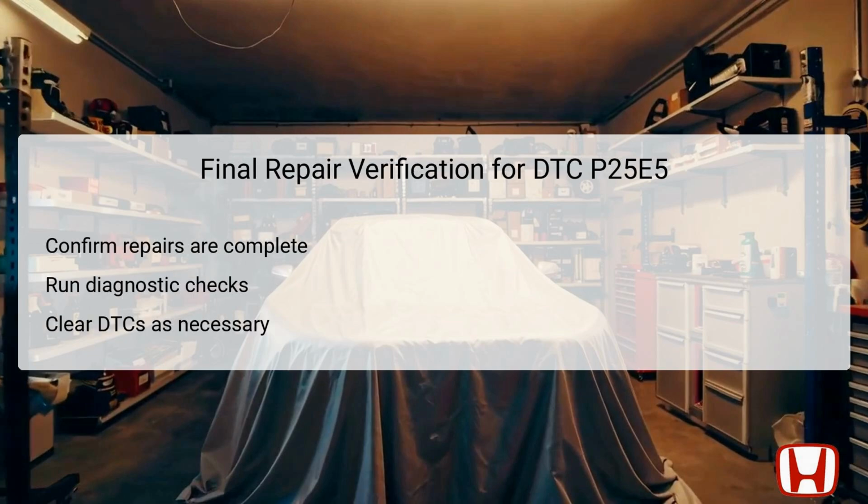After performing the necessary repairs indicated by the troubleshooting steps for DTC P25E5, a final verification of the repairs is essential. Begin by confirming that all recommended repairs have been properly conducted and that all components within the VTC system, including the solenoid valves and passages, are functioning. Subsequently, execute any diagnostic checks to ensure that the system operates smoothly without abnormal readings.